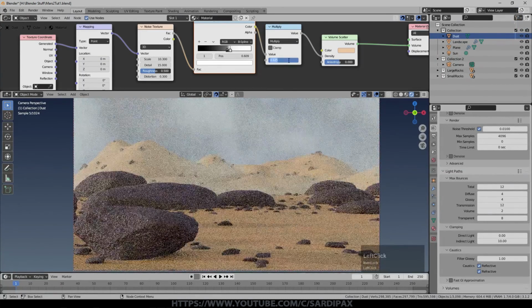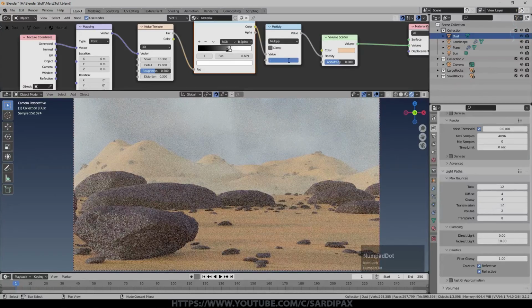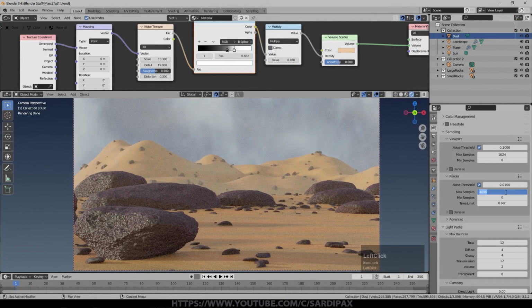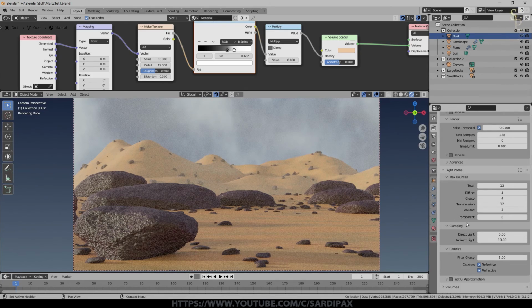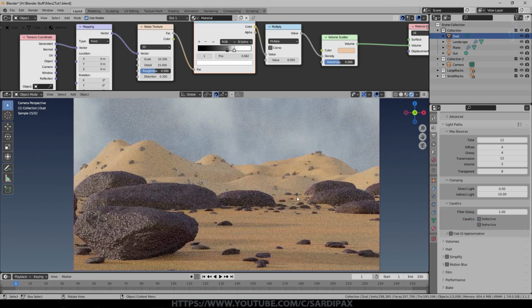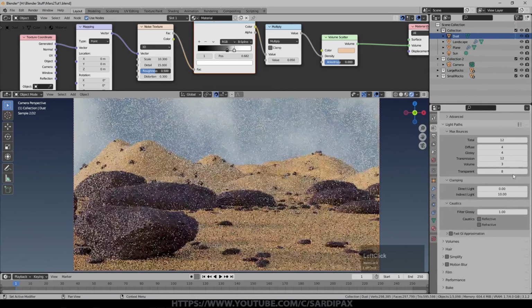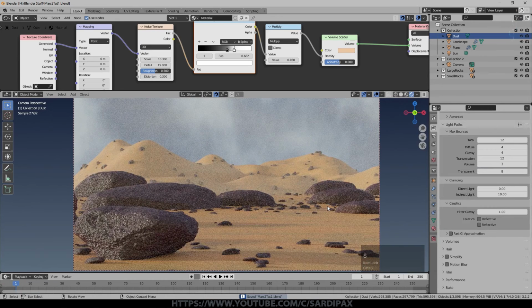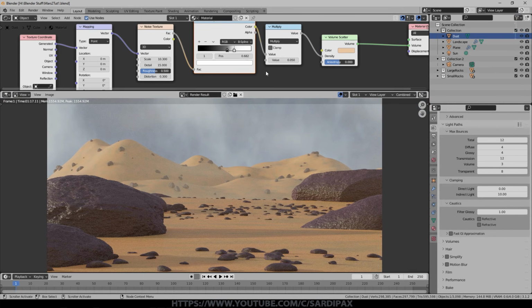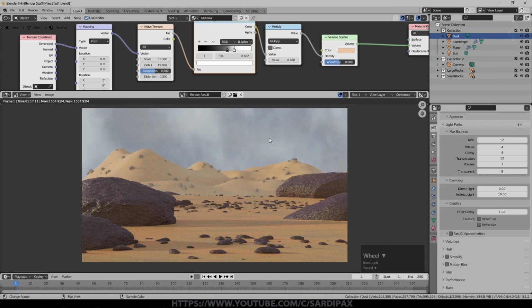and we'll turn the density back down again because we're not trying to simulate a sandstorm. If I give that a render, we can see what that looks like. So we'll just go 128 samples. We'll leave denoising off for the moment, but I will turn caustics off because we don't need them for a scene like this, and they do add noise. I've already increased volume. I'm going to go up one more, I think. So let's give that a render and see what it looks like. Okay, so that's not too bad. Probably need some tweaking to increase the contrast on that dust in the air slightly.